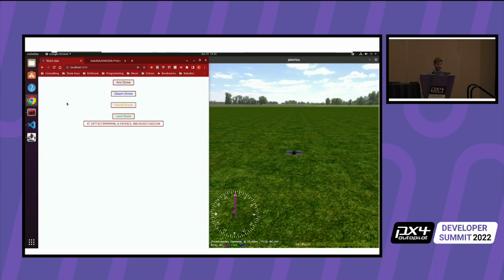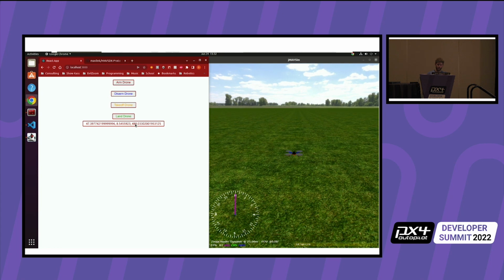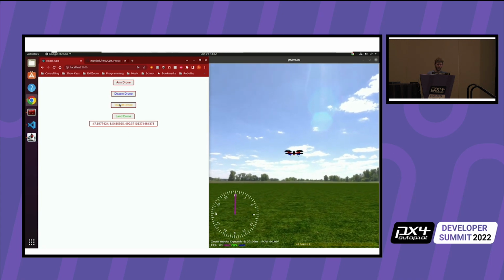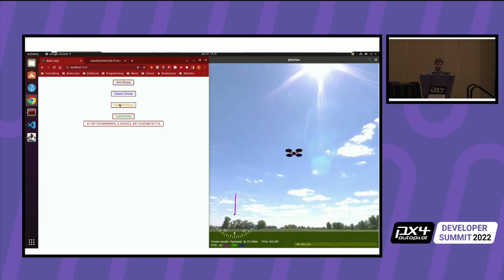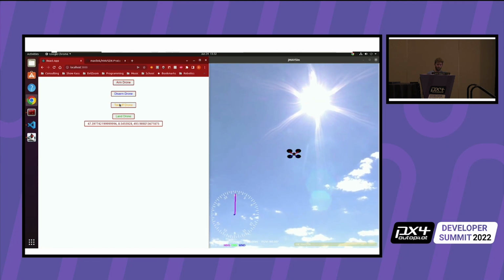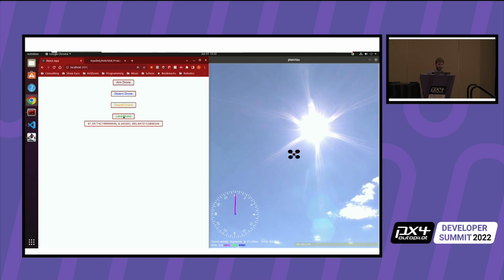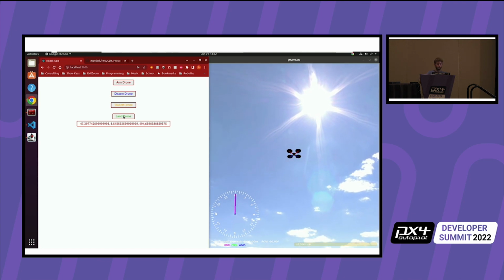It's so easy. Arm the drone, take off the drone, you should be able to see the altitude climb, and we can just keep taking the drone up to get a bigger difference so it's easier to see. Yep, so we're at 495 now. Land the drone, we should see it go back to that initial altitude.